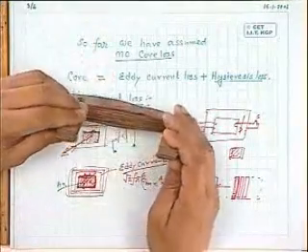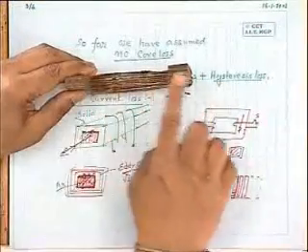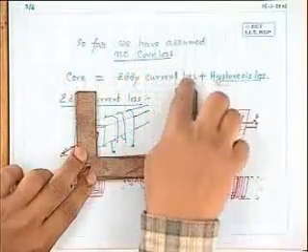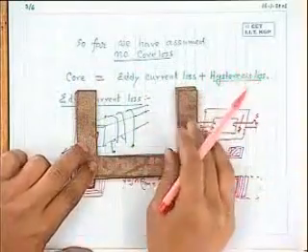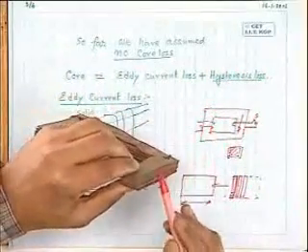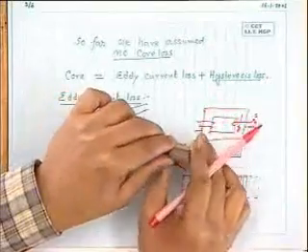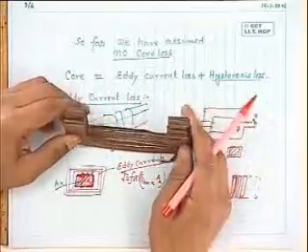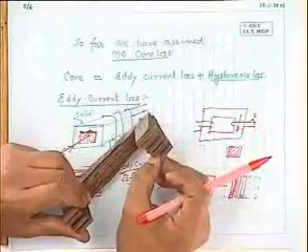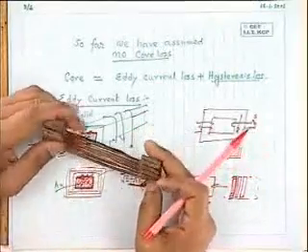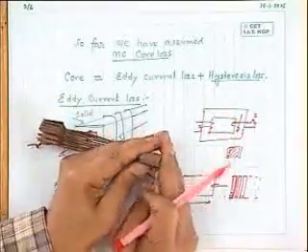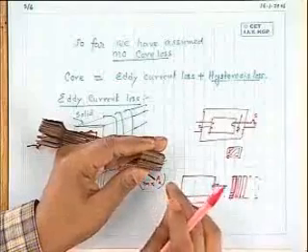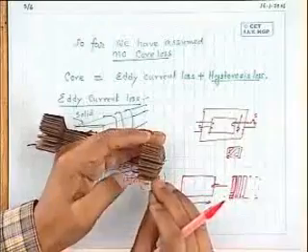In fact, suppose this top is not there. You imagine it is like this. This one is your magnetic structure. What is the cross-sectional area? It is this cross-sectional area. You could use a solid block of iron to make this complete iron structure. Instead of that, you are using plates of very small thickness, and you stack them together. Then this area can be realized, which you would get by using a solid block of iron.